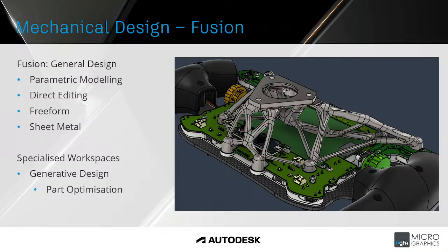If the machine has rotating components or components that need to essentially move, be driven by motors or hydraulics, the lighter the component is, the less effort is required to move that component as well. So here you can essentially increase cycle times on machines if the components are lighter and can move quicker. And so if you're producing machines that do mass production, you can up your cycle times or up your units produced by that machine because the cycle times are quicker. Or you can keep the cycle times the same, but require less energy to actually maintain that cycle time.